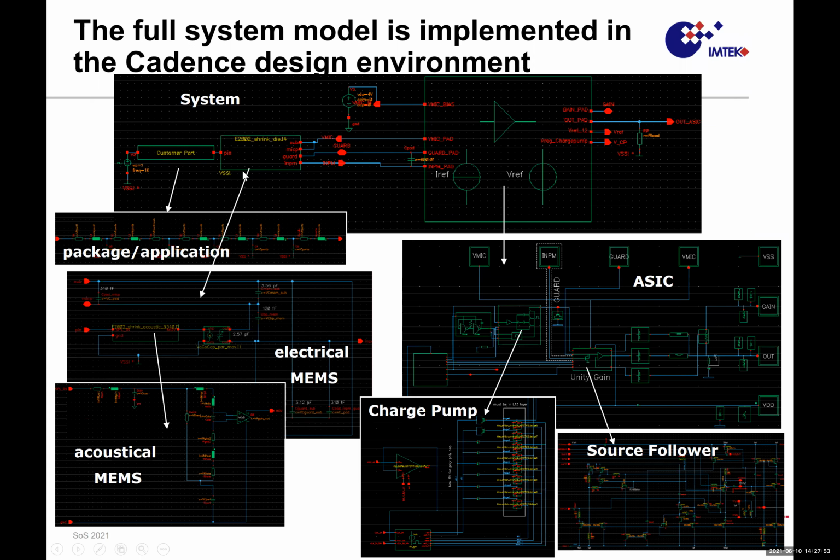Then we have the microphone total model, and here's the ASIC model to the outside. Yeah, and the ASIC model is of course detailed, starting with the customer port. You see here kind of a package specific circuitry. The microphone is exactly what we have discussed today. Finally, you find here the port and the diaphragm and the back volume, stuff like this, which we will discuss next time on a SPICE model maybe.